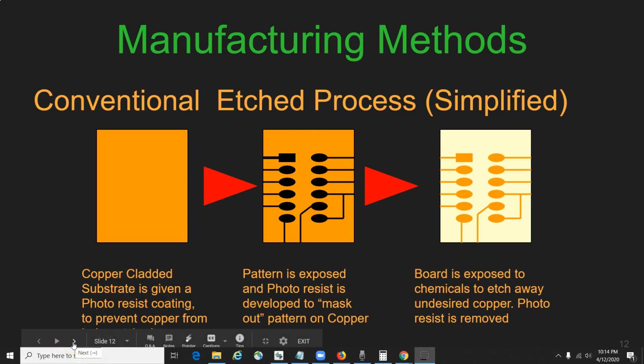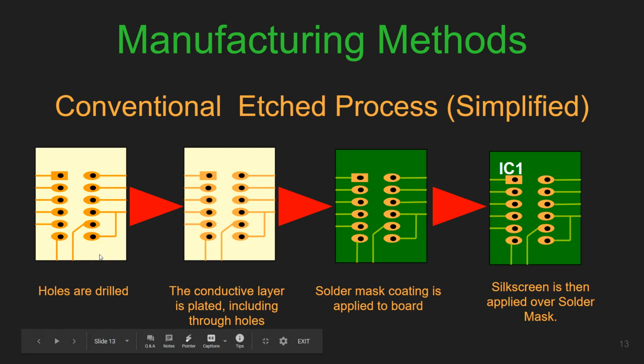And then you cut out the design and place it face down on the copper. And then you run the copper plate with the design face down through a laminator. It will take around 5 to 7 times until the plate is hot. And after running the plate through the laminator, or ironing the plate, you will put the plate into a cold bath and then agitate until the paper floats off.